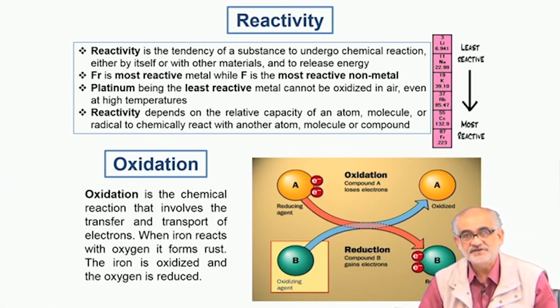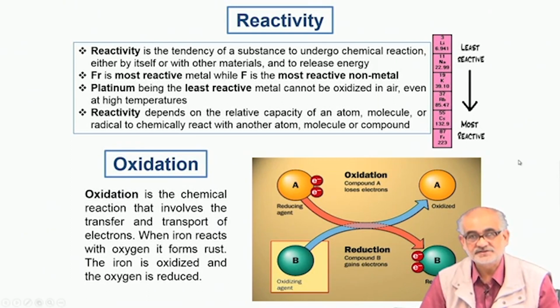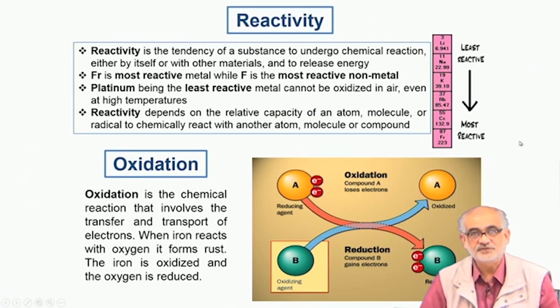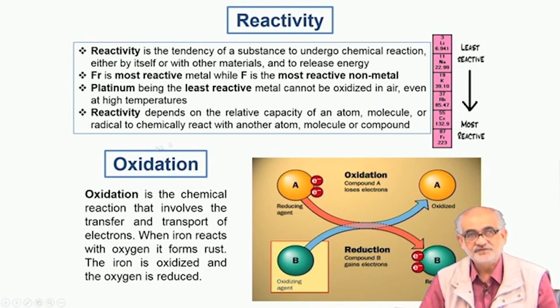From the atmosphere, we pick up certain anions, maybe oxygen, maybe chlorine, or some other kind of anions, and if we have a metal, or for that matter other solids, which is ready to offer certain cations, these anions and cations are likely to react immediately depending on their tendency of reaction, and the rate or degree of such reaction would be much higher at higher temperature, which is what happens in case of oxidation. This leads to gradual conversion of the solid into a different form, which is mostly undesirable, and we need to prevent it.